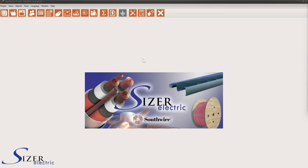In this video, we will show the operation of the module for circuit distribution on reels of the Sizer Electric software. In engineering practice, one of the most laborious tasks is to distribute the circuits on reels. These reels, in turn, have limitations on the maximum conductor length that can be accommodated, which are defined by the manufacturers. The objective is then to optimally utilize the cable within the reels while minimizing material losses. Let's see the principles of operation for this module.